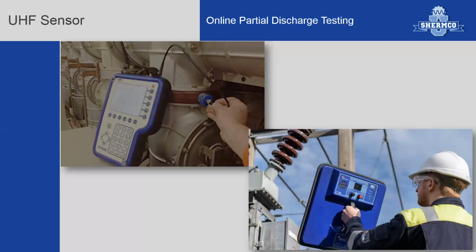Every time a partial discharge event occurs, electromagnetic waves are transmitted from the site of the defect. This emission may also be called RFI, radio frequency interference, or EMI, electromagnetic interference. The partial discharge emission is a broadband electromagnetic emission which can range from the upper radio frequency range up and into the microwave range. Again, typical bandwidths are around 300 megahertz out to about 1500 megahertz, depending upon the manufacturer of the sensor. Now, all types of partial discharge will produce electromagnetic emissions in the UHF range. In most cases, the UHF emission is detectable with the UHF sensor.